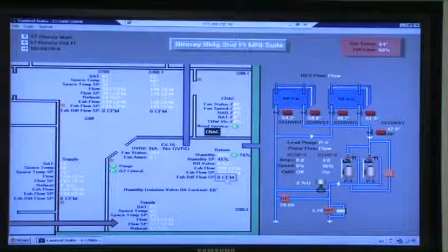Differential flow set point should be constant volume, so it doesn't matter what that does. And the exhaust flow set point, these two should go to 0. The set point will stay the same. It's going to keep trying to do its deal, but you're choking it off when you go to the approach condition. This should all say return instead of exhaust. Yep, that's right. And that should go to 0, and that should go on when that's an alarm here or that's an alarm.